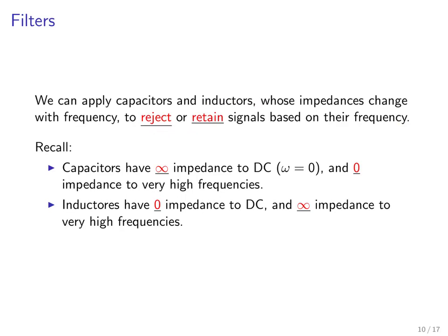So, for example, at some point soon we're going to be talking about having noise at 60 hertz, right? And you have signal maybe at 1 to 3 hertz. And so what you want to do is design a filter. What you'd like to do is suppress the noise without suppressing the signal. So you can imagine designing, using some arrangement of capacitors, resistors, and inductors, a filter that has essentially zero H of j omega at the 60 hertz frequency, but is all ones over that 1 to 3 hertz range where the signal is that you actually care about.